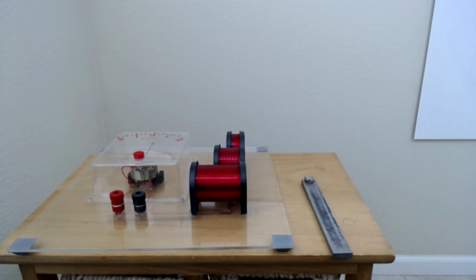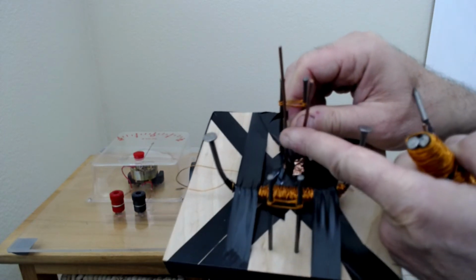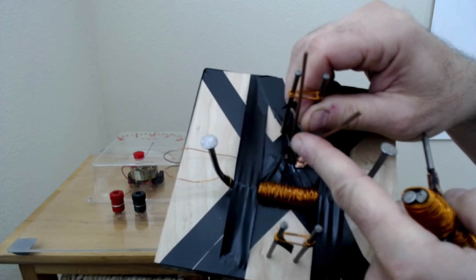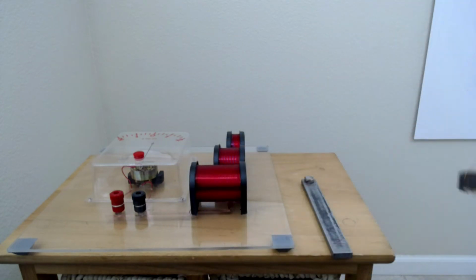So what you can do with your brushes is maybe try to use what this guy did. He used stiff wires for the brushes. This is a really simple motor, and you're working only at 1.12 volts. There's a lot of little things you can do to make this thing run well.